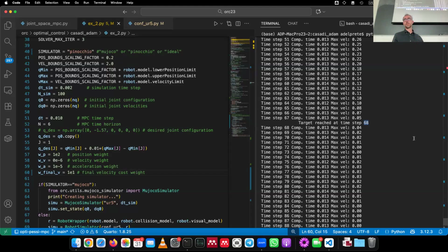Okay. You said that we can use the backward reachable set algorithm. Can we find such complex sets, like the walking set, with such an algorithm? No, not the example I just made, because that's not a backward reachable set. You could find a limit cycle very easily and use that as a control invariant set.